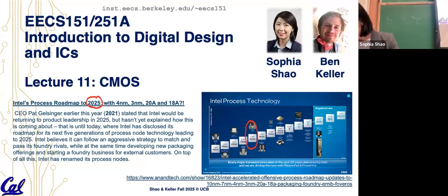Back then, Intel had this projection, and one of the biggest components they introduced is the angstrom era. They changed the unit from nanometer to the angstrom, A. An angstrom is basically a tenth of a nanometer. So far we have been going down like 16, 10, 7, 5, 2, but we'll get to 2 and there are just not many numbers you can play with. It's a little awkward to say N1.8, it's just a mouthful. So they switched the unit: instead of 1.8, it's 18A. Instead of 1.4, it's 14A. That's the new node naming for more advanced nodes.